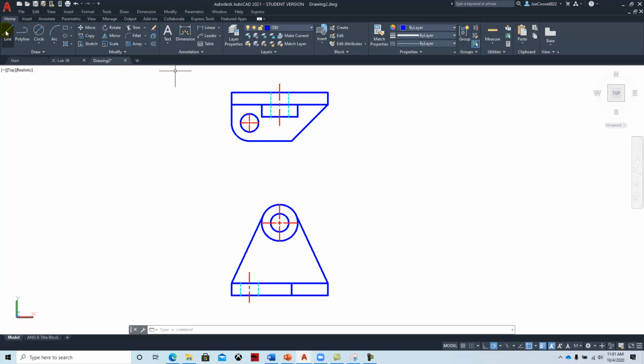And again, I'm going to make a miter line just from a standpoint of getting people to understand how it works. I'm just going to track this over. And then as I draw, I'll track this up. There's 15, 30, 45. And I just want it to go the length of the part. It can go a little bit farther if I track like this. And I'm almost getting my 45. There it is. It's the trifecta. And so then we'll go through and project over our side view.